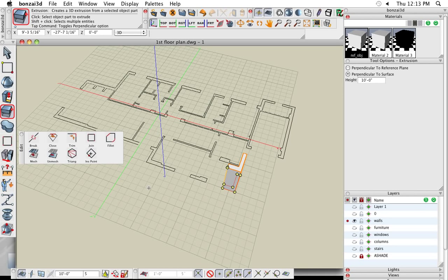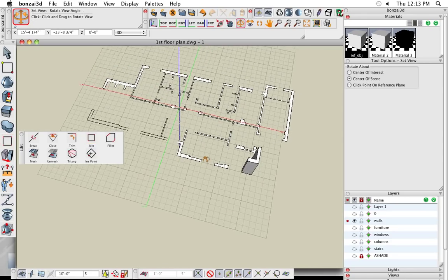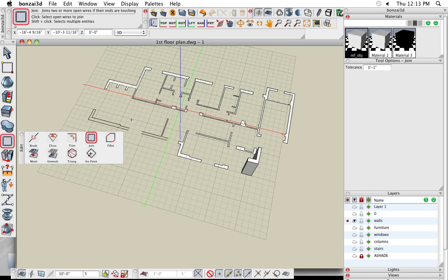So what I'll do is I'll do a Command A to pick everything. On the Windows machine, it's Control A. On Mac, it's Command A. It just picks all my objects. And then what I could do is pick the Join tool, and I click a blank area. And somehow it magically looks at whatever I currently had picked and tries to find a series of closed type segments. So it joins all those together. It's just that easy.